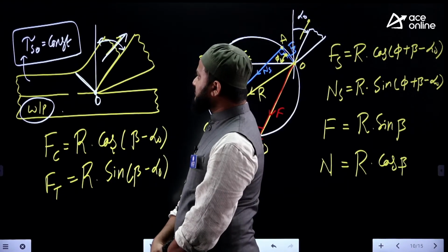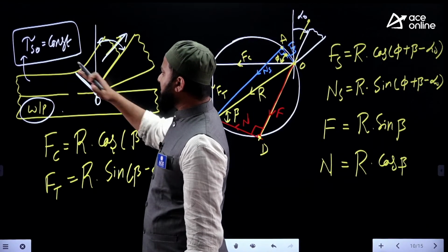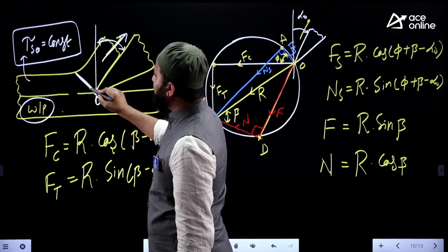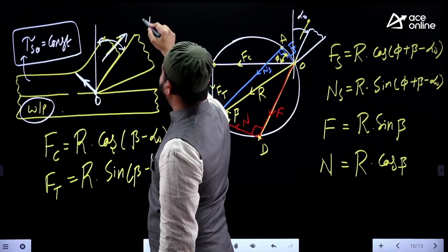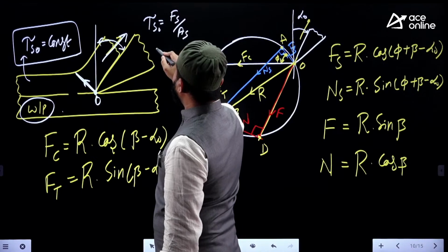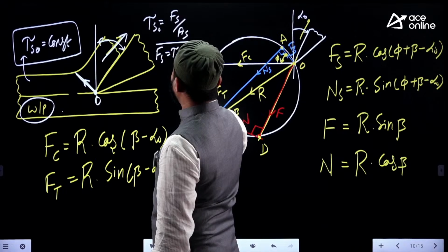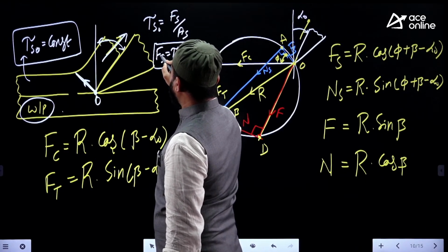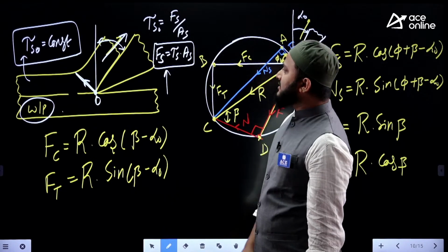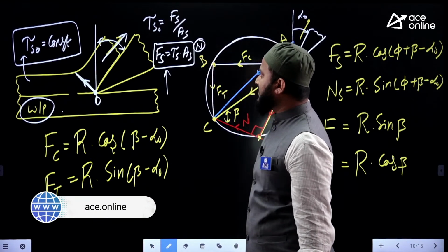So when shear strength is constant, in this particular plane, which is perpendicular to our screen, we get a shear plane area. So shear force by shear plane area, that itself is the shear strength. It means the force required for breaking this unwanted metal, we can calculate that shear force from the shear strength of the workpiece and the shear plane area, and the unit will be Newton.